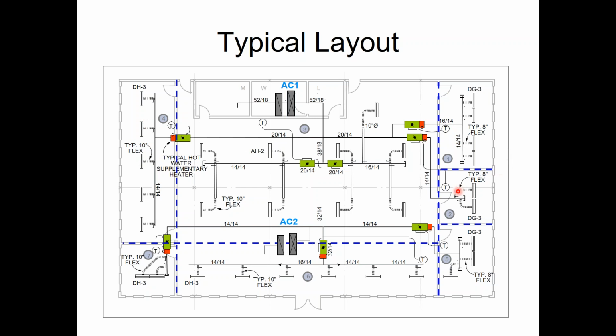I don't want east and west mixed together at all. And I don't want interior and perimeter mixed together at all. It's going to be a problem. Interior, these guys over here always want cooling. But when this guy wants heating on the outside, I can't do both. I can't do heating and cooling. Can't do it.